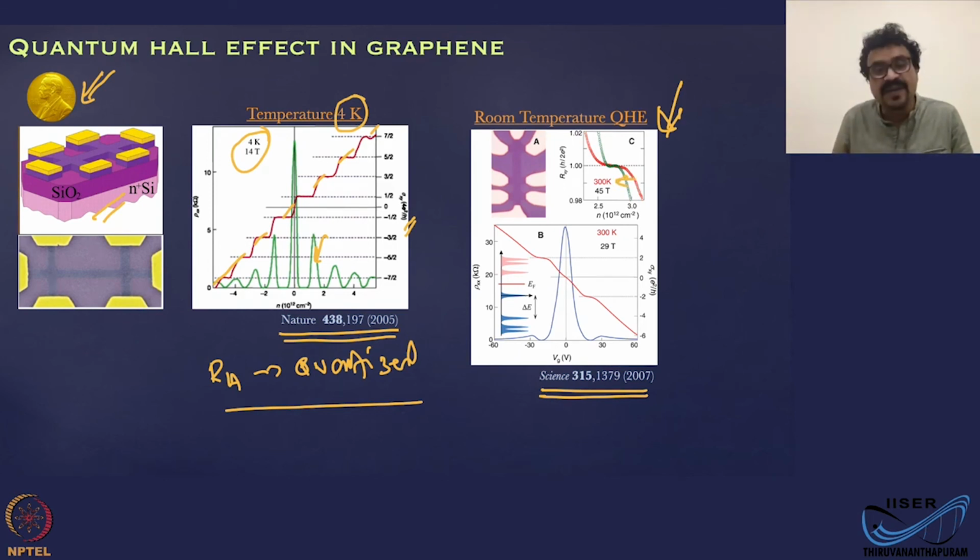That is awesome. So what we have now is, you have seen this effect starting from a silicon MOSFET. Then we moved on to gallium arsenide heterostructure, two-dimensional electron system. There also we saw the same effect. And now there is another completely different two-dimensional system. It is radically different. The first two are bulk two-dimensional systems or interfaces in the bulk material, but this is actually a pure sheet of atoms. There also you are seeing the same effect, the quantization, and it's so robust.